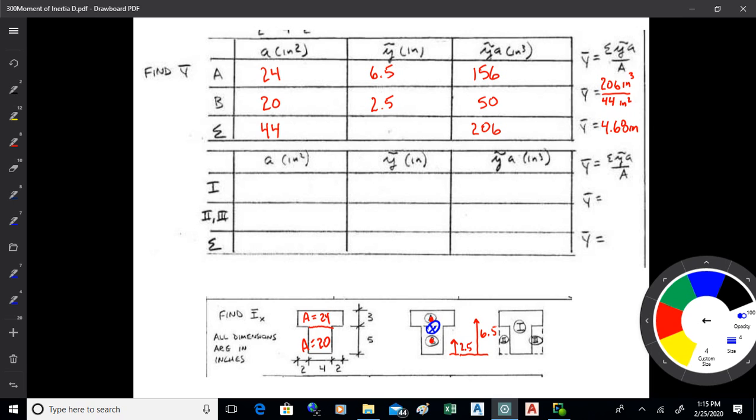I was walking into the meeting with the coordinates that the person on the computer had just generated, and the clients are there, and there just happened to be a map on the wall. So as I was walking in, I looked at that latitude and longitude on the map, and we were going to put that bridge piling in Oregon, and the thing belonged in Alaska. There was just something wrong with that, you know. So I was a little late to that meeting, but I got it turned around and straightened out. So that common sense check, again, that's a good thing to do, all right?